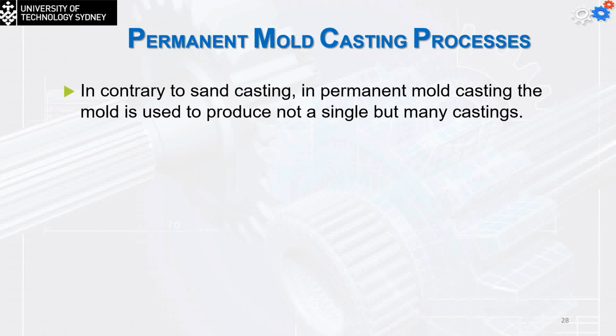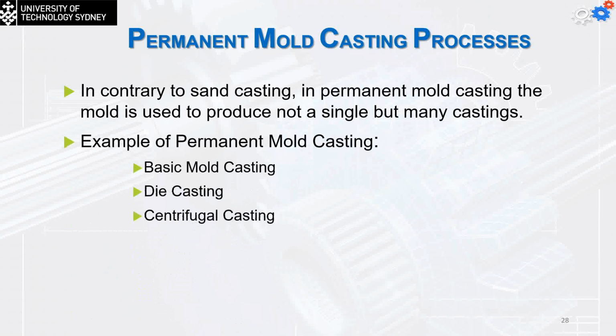The die casting, the one which uses the pressure. We're going to use the pressure to force the metal in. The biggest advantage of this one is the good surface finish, plus it's not going to shrink because it's always going to be under constant pressure. We always fill with the molten metal, so it's going to have the exact shape.